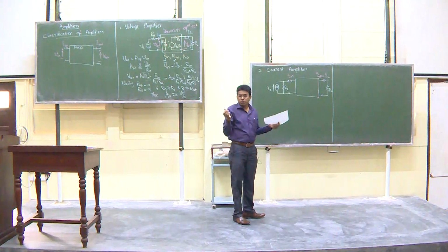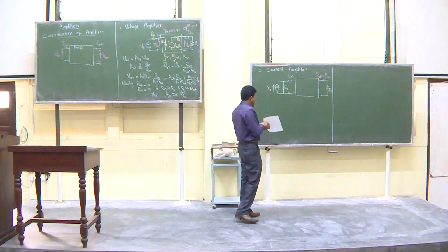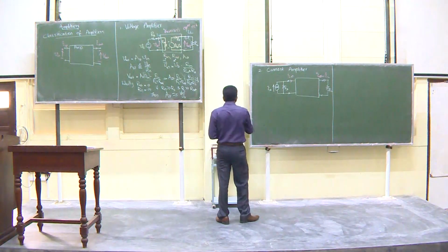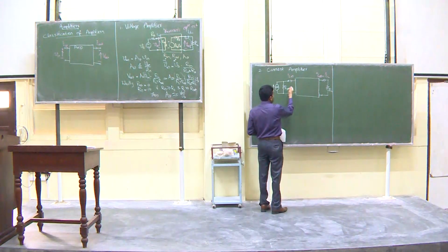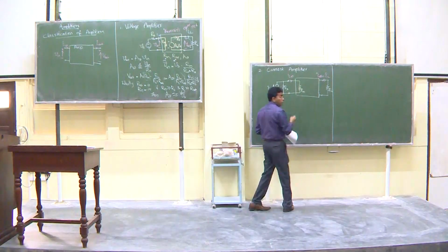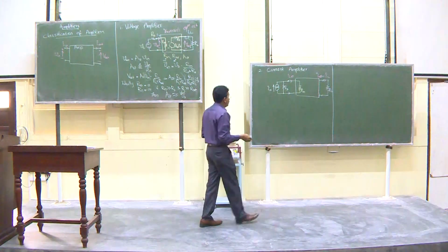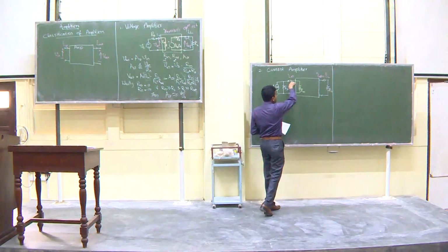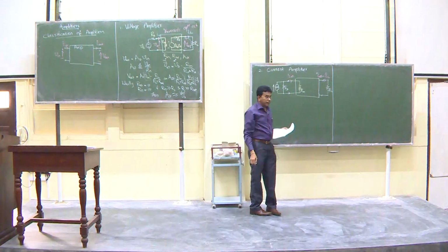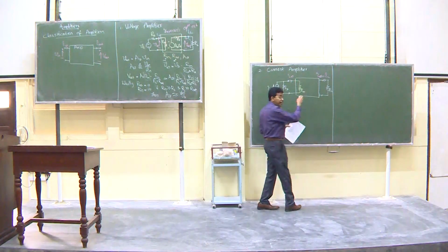Voltages I really do not mind what the value is. The first thing that we need to again say is, as soon as I connect here, it might load the circuit because of the input impedance, right. So, therefore, I am going to draw some current based on that. Second of all, the output has to be a current.